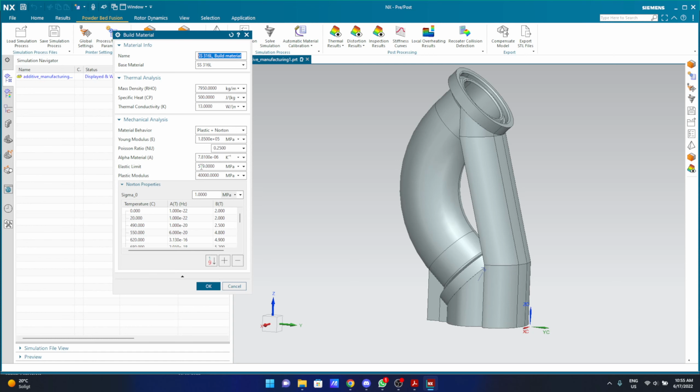The elastic limit was low and then they rounded it up to 800. It was about 750 or something. So I did the same thing for this. Instead of 519, I used 600. You can use any value that you want, like 550 or something else. You just need to mention in your report that these values were not given by default in NX. So we just use these values and that's how we are moving.